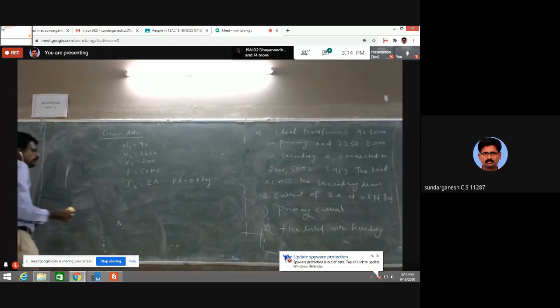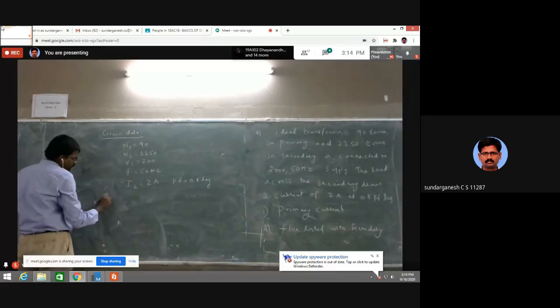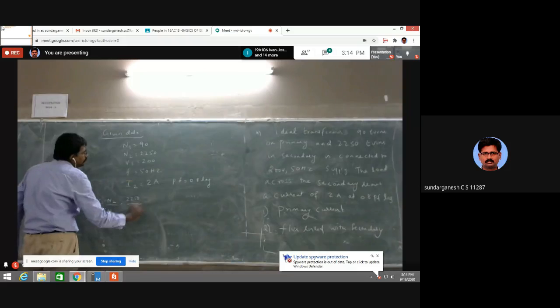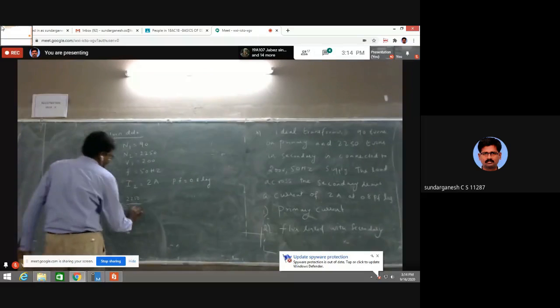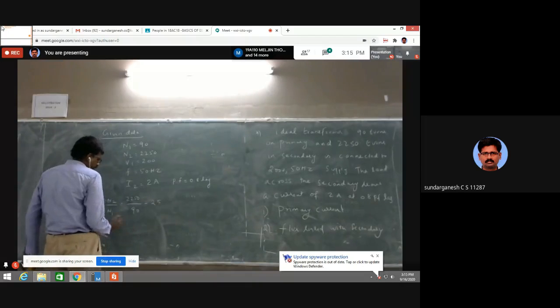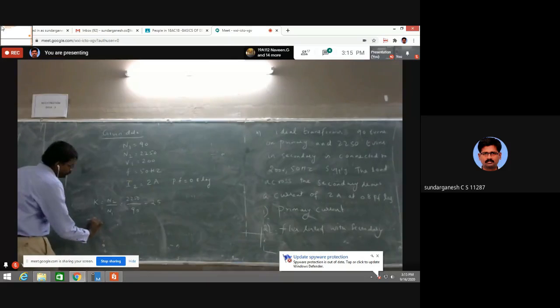We have the formula K equal to N2 by N1. K equals 2250 by 90, so the K value is 25. Then you can easily find V2.